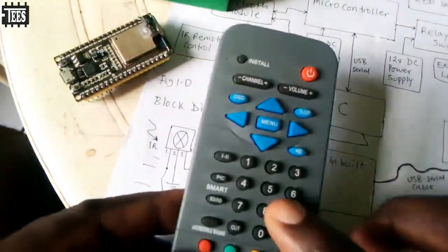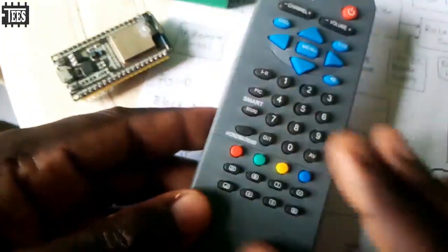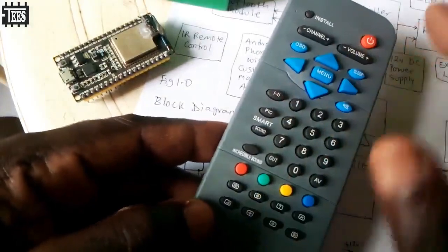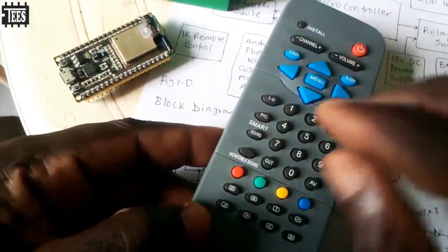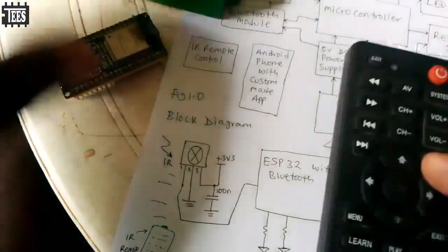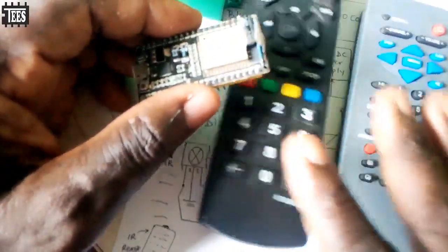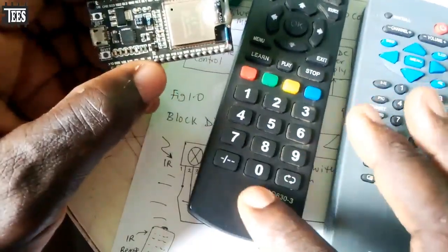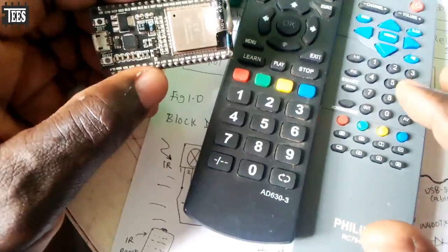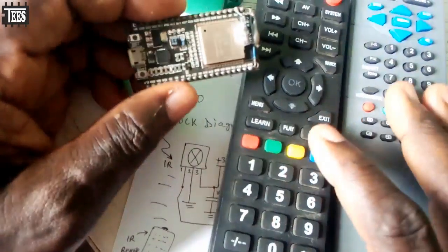So each one of these buttons transmits two things. Number one is the protocol of that remote control, and then the value of that particular button. So it's the value of the button which we need to use in your program. If I'm to use this, I will have to decode this and write a program for this and then add it here. I can add any number of remote controls, but make sure they have different protocols. Like this is NEC, this is Philips. We also have Sony. We have different protocols. I can add as many remote controls as I want. If I want to add this, I can write a program for this and then add it to this.